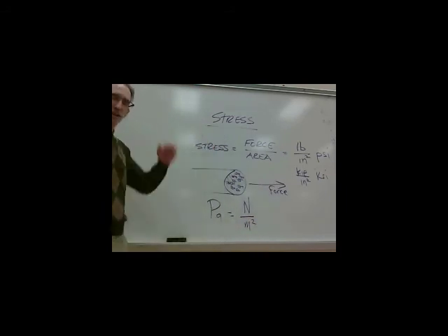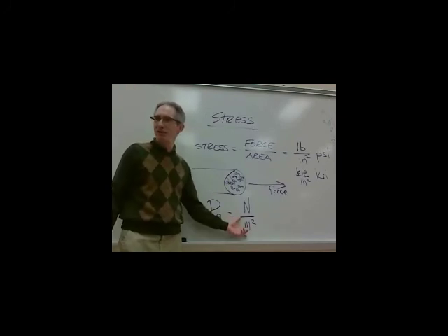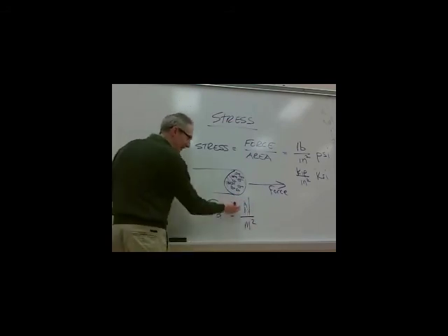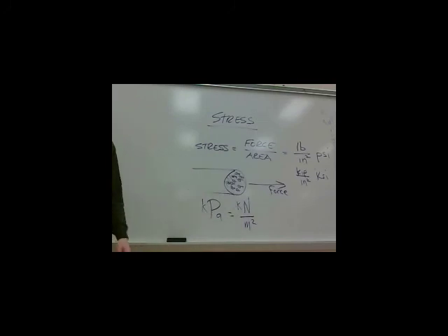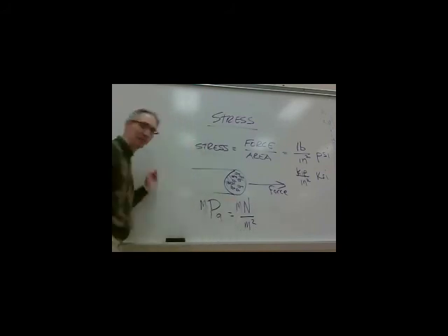So when I do problems, I always make sure my area is in meters squared, because that makes it easy. And if it was a kilopascal, just make sure that it's a kilonewton per meter squared. If it's a megapascal, just make sure that it's a meganewton. That's the way I always think about this stuff.